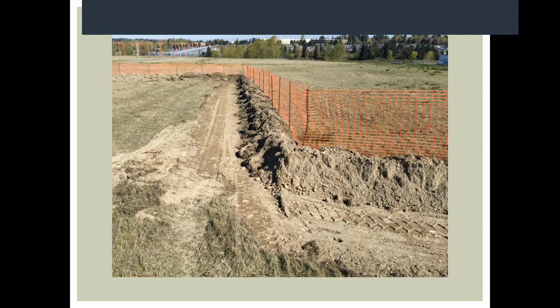This one may not look good. Maybe the original plan would have called for silt fence, but the fact that they were going to be scraping below the surrounding grade, and they were going to be able to push up a sod berm on the edges, then really the only issue is to put up a fence to keep people and equipment from wandering into other areas, and to keep people from tripping over the berm, I guess. So all that's needed is safety fence in this case, no silt fence.